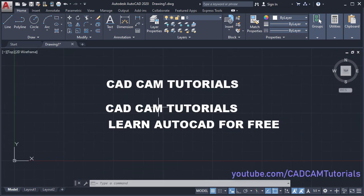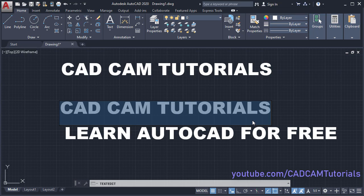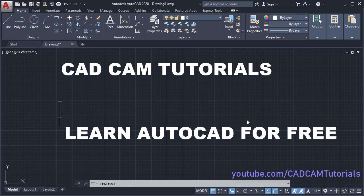Then if you want to add some special symbols like diameter, plus, minus, degree and so on, then for that again to edit we will just double click on it. And suppose we will remove all this text, press delete button for that. Suppose I want to write dia 10. So for diameter you will have to type %% and C. Once you type C, that diameter symbol will get created. So here is dia 10.